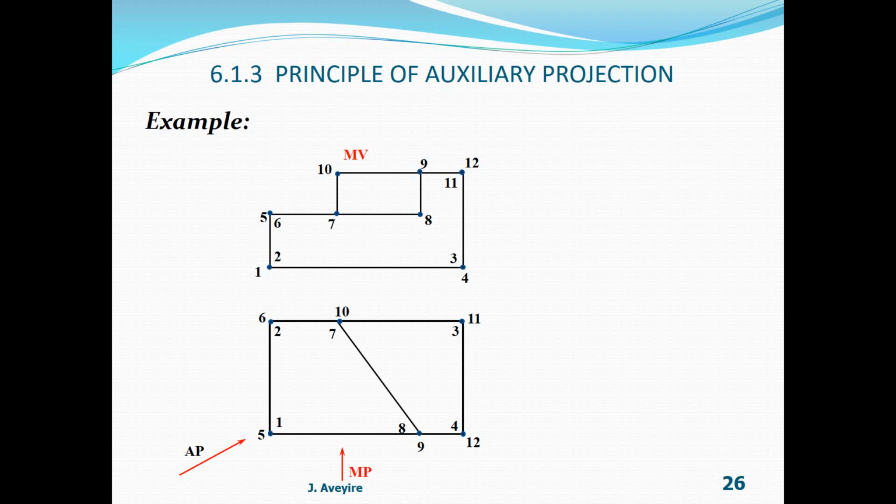Then we need to introduce our reference plane XY. XY is introduced here, and it is perpendicular to MP and at a convenient location passing through the points 1 and 4, so that in measuring distances from XY, all points above XY based on the vector MP are positive, whereas all points below XY based on the vector MP would be negative, but unfortunately there is none below.